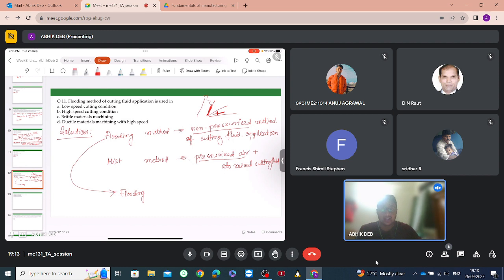Even if a high temperature situation is happening in the machining of some particular application, whatever it is, and some high temperature is attained within the cutting zone, flooding may or may not be beneficial depending on what the cutting speed is in that situation.